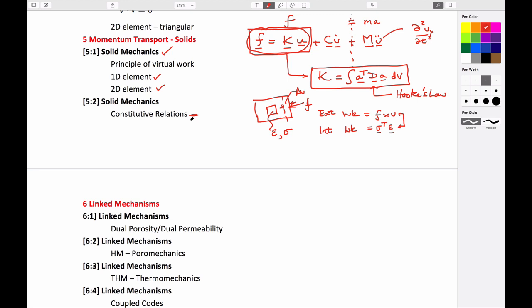But if we do that for solid mechanics problems, we have two behaviors to accommodate. One is where the displacements in the plane perpendicular for a two-dimensional problem are 0. In other words, imagine all of these lamina, such as for a dam, repeating themselves. So you take a two-dimensional cross-section of a dam that goes an infinite length into the page, then a single lamina can't expand relative to the sheet next door to it, because that sheet is trying to expand at the same time.